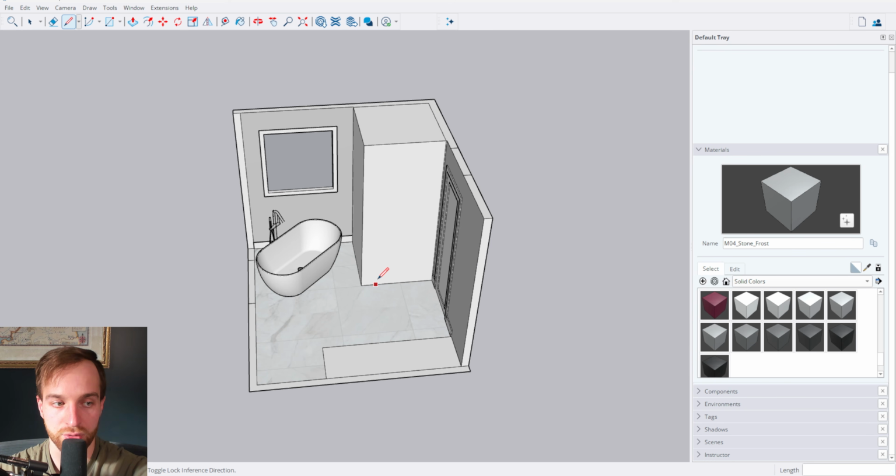And then from here, for my rough idea, I think the door would work nicely here. I'll do a very standard shower door size of 24 inches. You could go up to 26, of course, but for right now, we'll just keep that at 24. Draw a line down. I know from experience, we're going to have the gap at the top of our door. Our fixed panels will go to the ceiling. So I'm going to have a gap of, let's say, 12 inches.